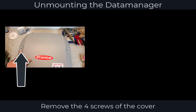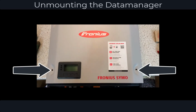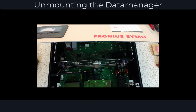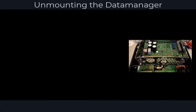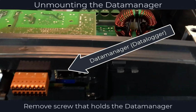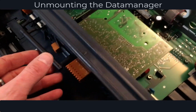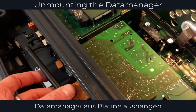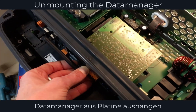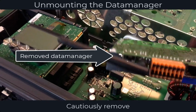Firstly, remove the 4 screws that hold the front cover in place. Secondly, remove the front cover by lifting it on the lower side and then levering it out of those hooks on the upper side of the inverter. Now, remove the 1 screw that holds the data manager in place. Carefully remove the data manager from the slot. It might help to gently move it slightly to the left and to the right. Remove it by pushing the antenna part through the hole, as depicted.